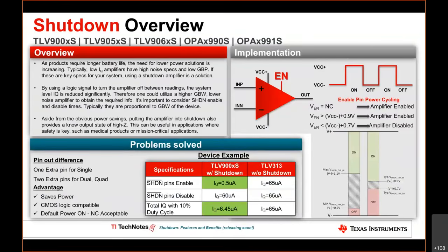Now, within the market today, I estimate that only about 10% of devices have shutdown capability. This is where you take 1 extra pin for single channels or 2 extra pins for dual or quad channel, and you have an enable logic pin that allows you to turn the amplifier on or off without disconnecting the supply voltage.